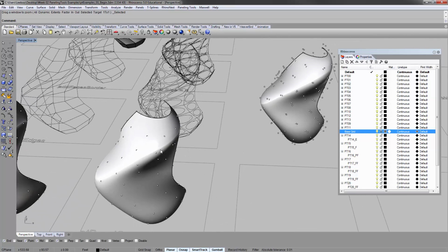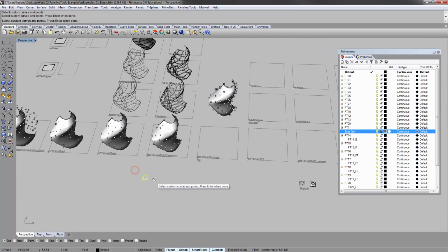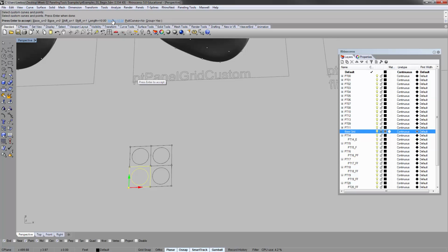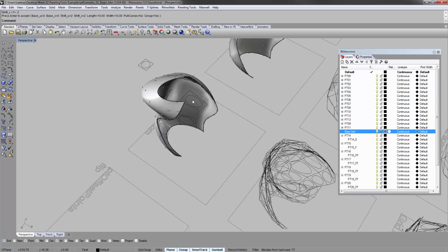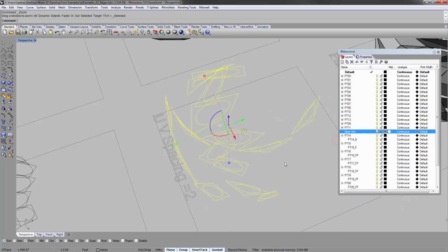The last option here is the UV spacing. So let's try that again. You should be pretty used to this by now. Okay, so let's zoom in here. Length and width are still 10, okay? But let's try Shift U, changing that to 2, and then Shift V, changing that to 2. You'll see the representation starts skipping every other in this pattern. And if we continue with it, what you'll get is something like this.